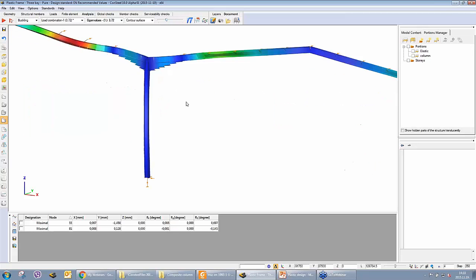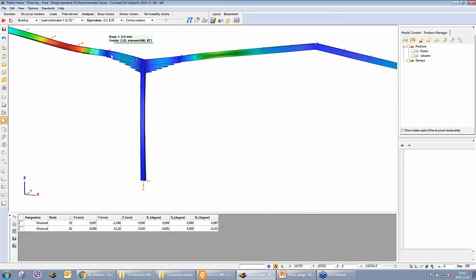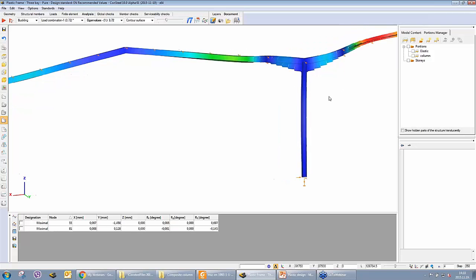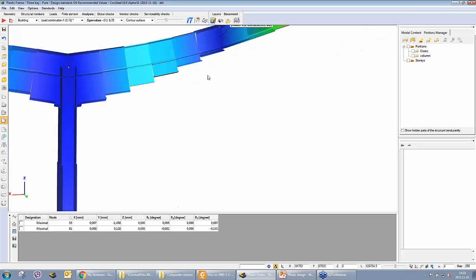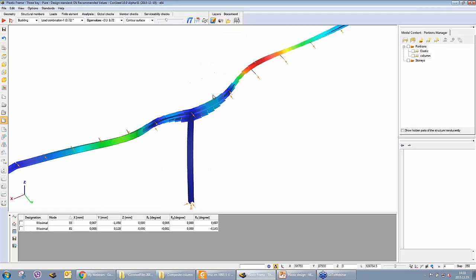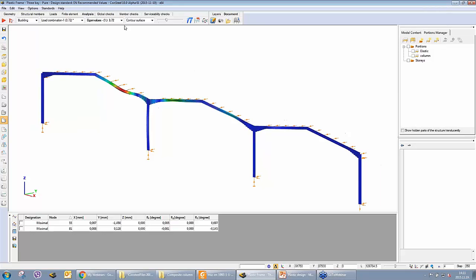What we see is that the dominant buckling mode is lateral torsional buckling of the beams just around this end position of the haunch, where we have the complete support at this cross section. We can see this two wave-like buckling shape. So this is the dominant buckling mode at a critical load level equal to 3.72.